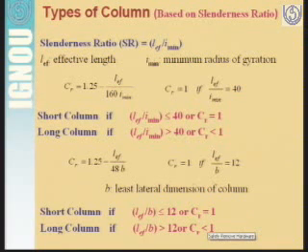And this value of 12 comes from here. You see, this is a factor Cr equal to 1.25 minus L effective, meaning effective length, divided by 48B, where B is the least lateral dimension. So Cr will be 1 if the ratio of effective length to the least lateral dimension of the column is 12. Taking this from the formula, we classify the column as short or long.